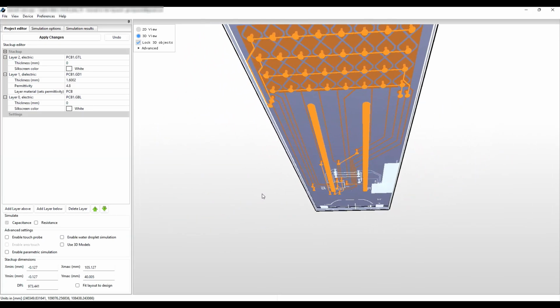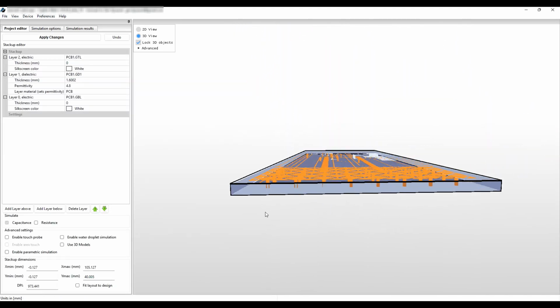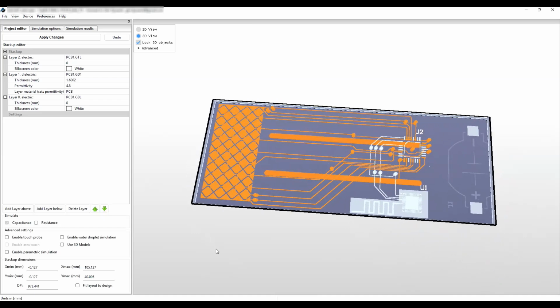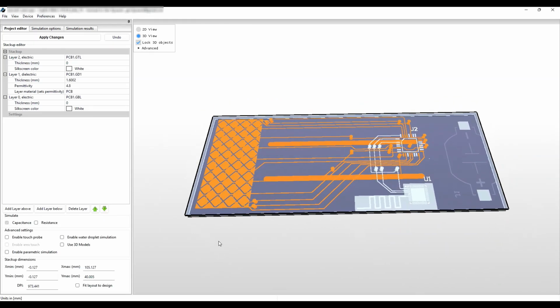For a board that doesn't have complex 3D structures that are affecting the touch design, this is how you will evaluate the design in its entirety. So for users that don't need the design to be prototyped in a 3D environment, tutorial videos 1 and 2 should cover most of your design flow. Most designs do not have touch on both sides of the PCB, and for these designs, adding a single overlay on the top part of the PCB is sufficient.